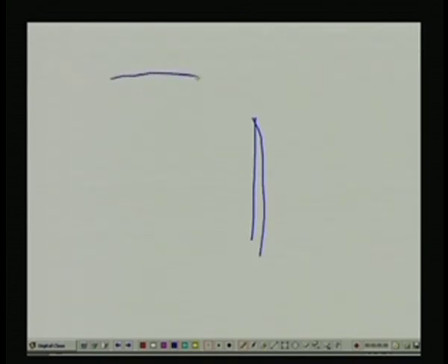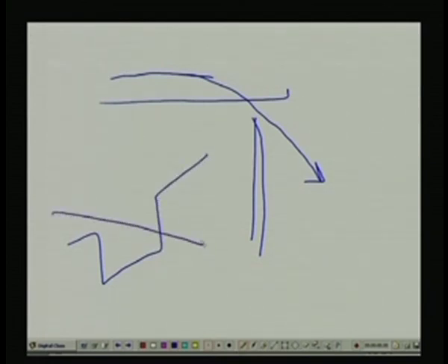So, there is not that suddenly it is coming. It is a slow contraction from the top, and we are assuming that all flow velocity is like this, like if I have a weir, we are assuming that all the velocity is in this direction. This is not necessarily true. Velocity will be in this direction, and some velocity will be in these directions also, right. So, you have to take care if we are interested to find the actual flow rate.